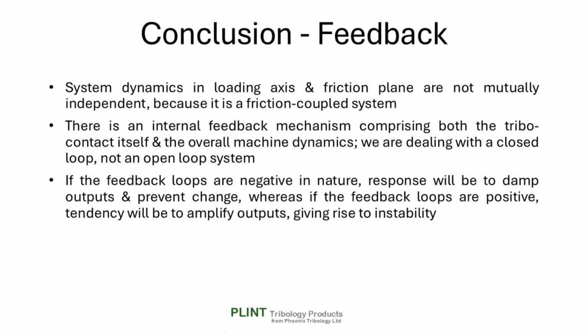Thinking about system feedback, it seems potentially attractive to treat the system dynamics in the loading axis and the friction plane as mutually independent. However, this is clearly unrealistic because frictional response is dependent on load. We have a friction and wear coupled system. There is an internal feedback mechanism comprising both the tribo contact itself and the overall machine dynamics.